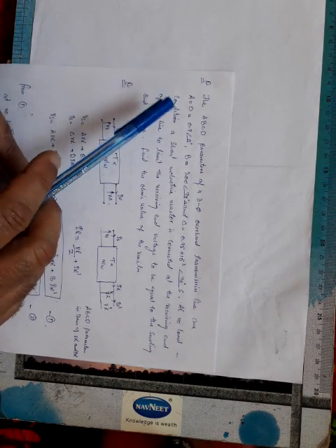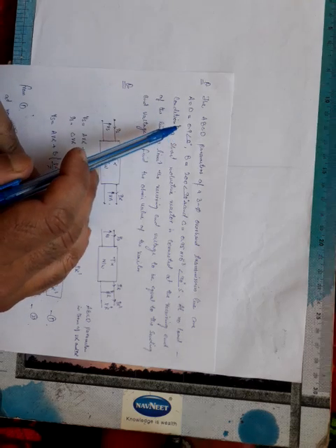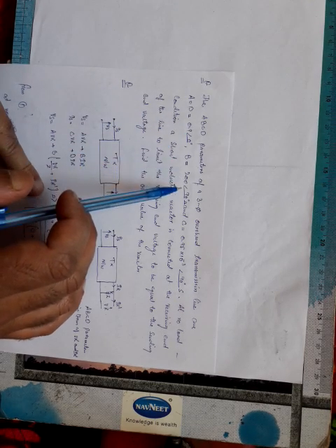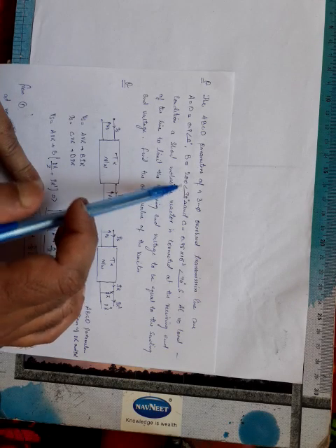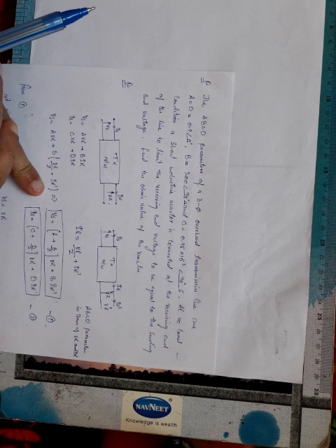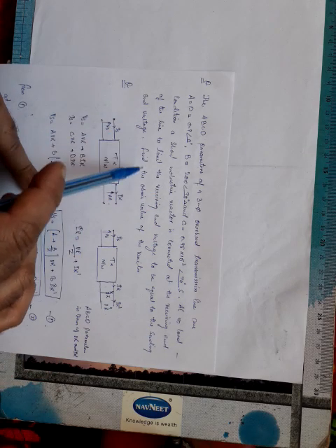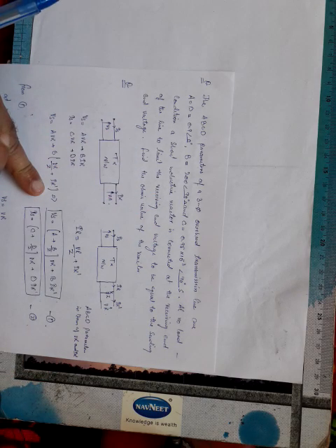The question is, the ABCD parameters of a three-phase overhead transmission line are: A is equal to D, 0.9 angle of 0, B is equal to 200 angle of 90, that is 200 j, and C is equal to 0.95 into 10 to the power minus 3 angle of 90 S, is the shunt admittance, neglecting the conductance. At no load condition, a shunt inductor is connected at the receiving end of the line to limit the receiving end voltage to be equal to the sending end voltage. Find the ohmic value of the reactor.